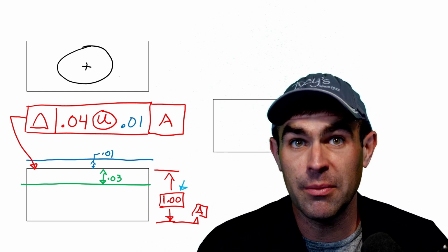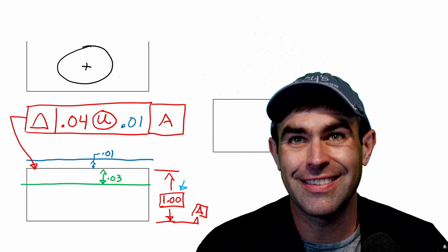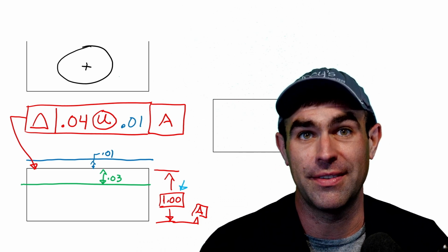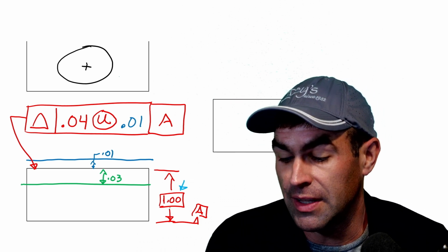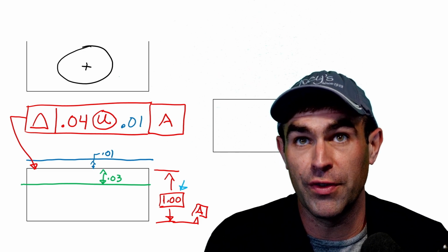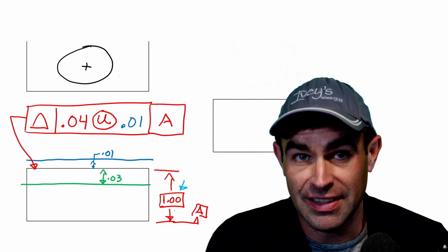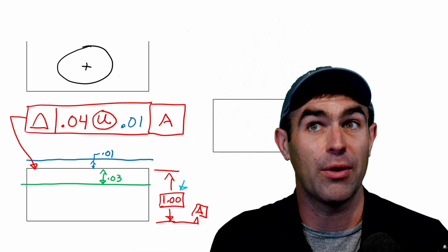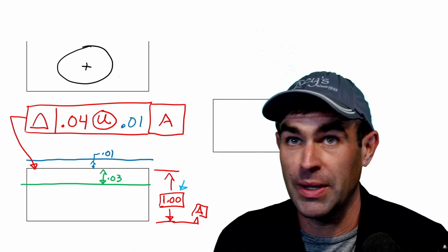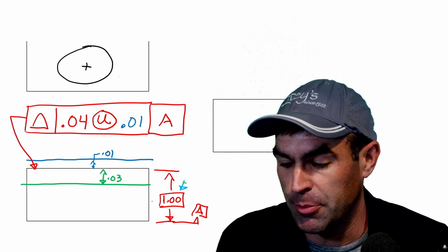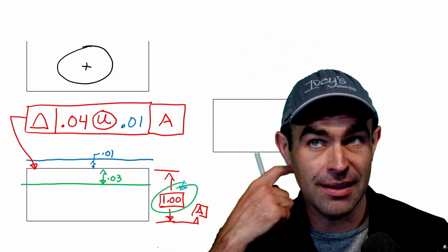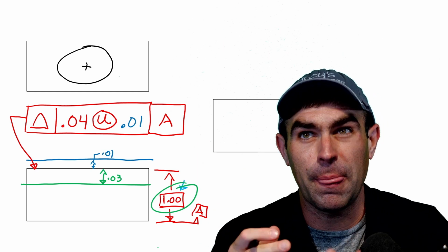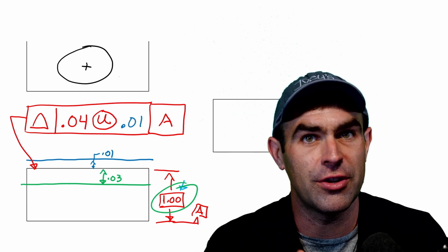This works fine, but it's easier sometimes just to move that basic dimension. This would mean the same thing if we just move this basic dimension down 10 thousandths, then we could just have a profile of 40 thousandths. Just depends what your design is doing. Sometimes people like round numbers, and I get it. In any case, your tolerance zone boundaries don't change, right?